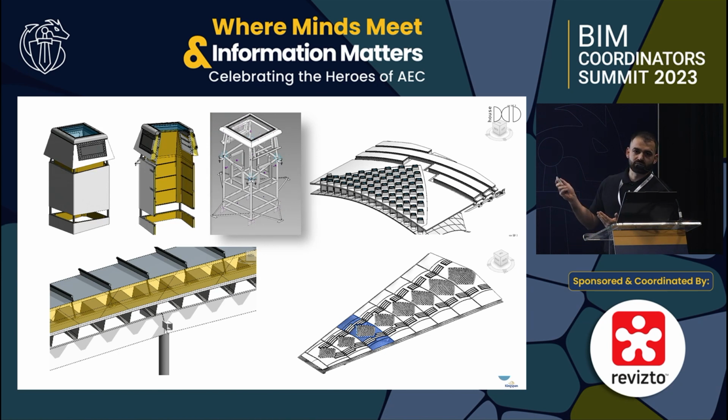And I was working here with Kingspan during the time with my team. We did highlight one of the bigger challenges, which is the skylight. If you see this build-up on the funnel on the left-hand side, this is a funnel that goes through the roof attic. There are 7,922 of these funnels in the project, and they're all different in height and width. So the only way to do it was to build one prototype, have some adaptive points with formulas that can script this prototype and mainstream it through all the skylight locations.